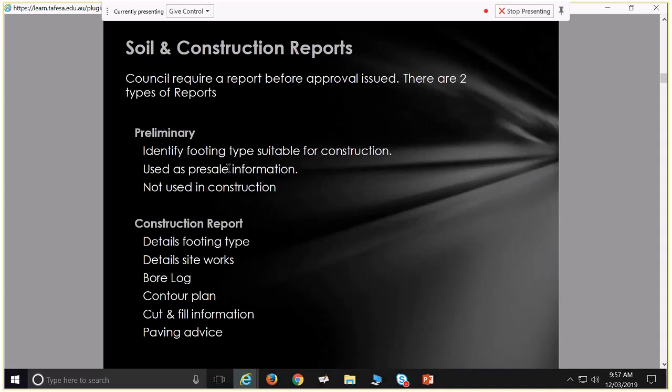But with our reactive soils, it's very important that you do direct moisture away from the building. So any water that's coming down near the building, that's directed away. So typically with the slab design, engineers are also going to specify paving details for that property as well, to ensure that you have impervious paving, so either concrete pavers or concrete slab paving around the edge of your building, and that's going to slope away from your building to direct moisture away.